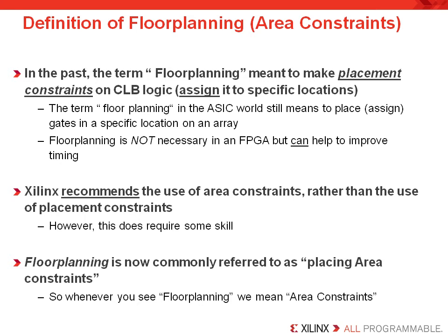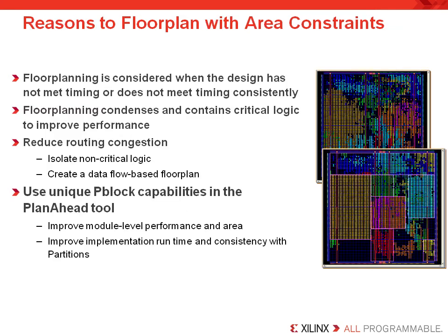As a caution, whenever you hear the word floor plan, it's about area constraints, as these terms are still frequently confused. Floor planning may be considered when a design does not meet timing consistently, or when the design has never met timing.